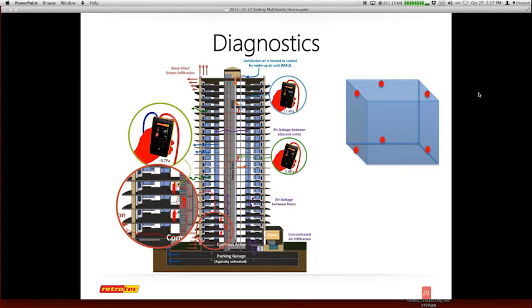So one of the things you really want to make sure of is that you can go through just with your gauge alone and determine what kind of pressure differences you have between, again, the unit, the floor, the common area, and the stairwell, and even down to outside. So you can determine a lot about how the structure is actually working in its natural condition, which is hard to do on a residential structure in terms of the type of pressures.